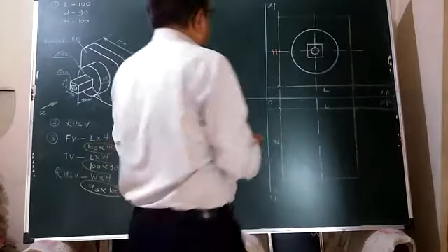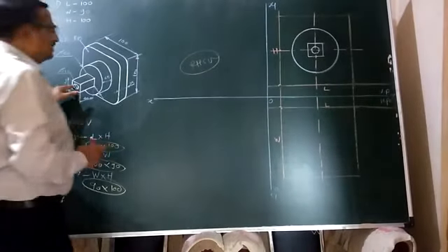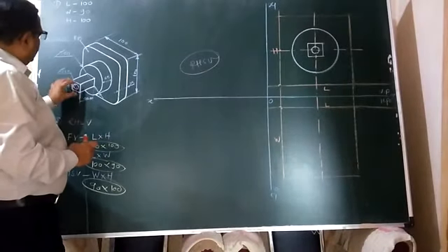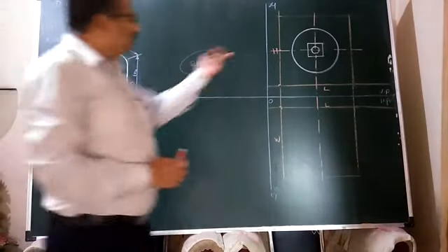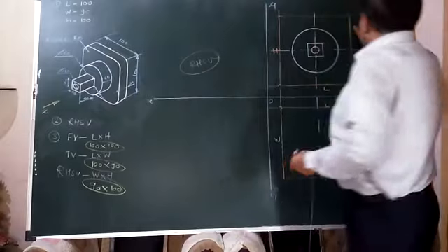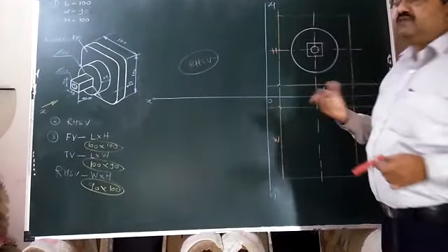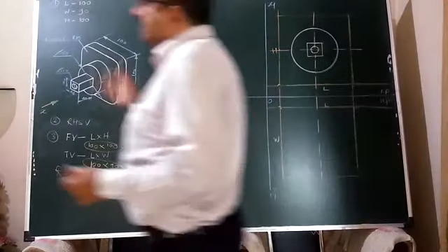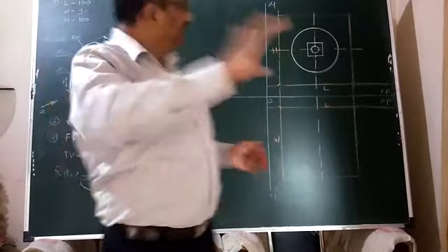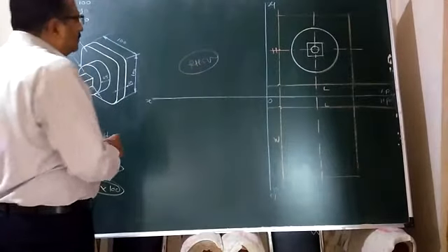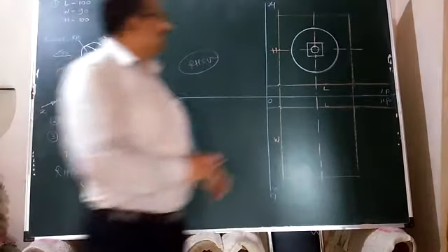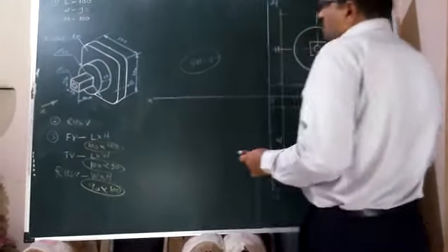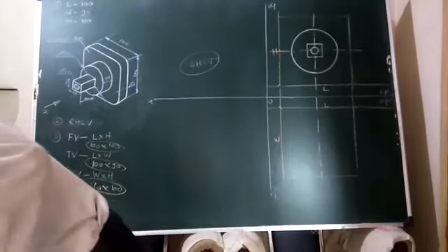Okay, yes. So at a glance, this circle will be appearing, this square that I have shown, this elliptical in 3D, but it is converted into circular in 2D. Okay, that we discussed last time. Anything which appears elliptical in 3D is naturally circular in 2D. Okay, now the last task is to create the curvatures at all the four corners carrying 15 mm radius. Then how to fit those curvatures? The parallel method we have learned.